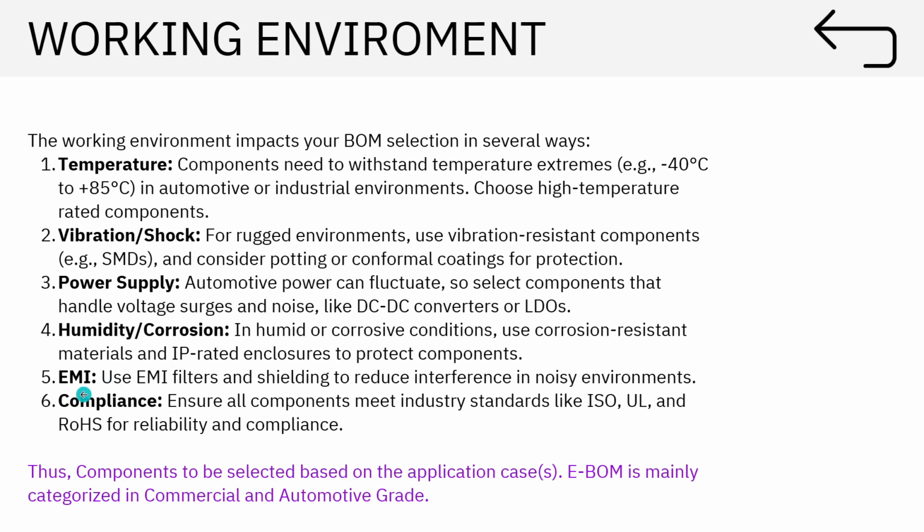Then you have EMI/EMC. Let's say this hardware is going to get deployed near a high voltage system, or somewhere there is a lot of electromagnetic interference. So you have to have proper shielding done, or proper protection done on the hardware itself, or on the schematic, or on the PCB itself.